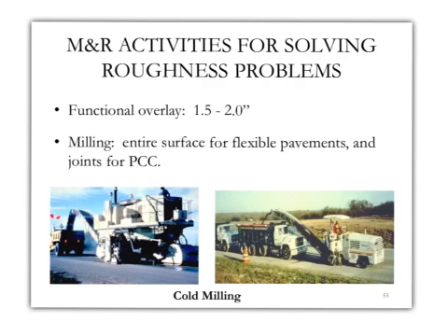The remaining question here regarding roughness, after we got to know how to measure it and what the devices to use are and what the conditions to be aware of while measuring roughness are, is now how can we fix it? So, what are the typical maintenance and rehabilitation activities for solving roughness problems? First of all, we need to remember that roughness is mainly affecting the functional performance of the pavement. Therefore, the entire structure, I'm assuming, is well and very healthy. The only thing that I need to worry about is the top 1 or 2 inches,